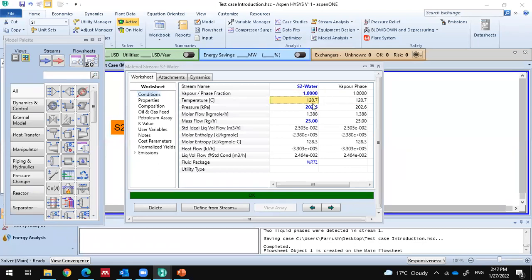However, since it is, as I told you, the saturation line, the temperature is constant. You need to add the latent heat of vaporization, or remove the latent heat of vaporization for condensation. So the temperature is going to be the same. Let us say for now we put it as 0, and we say that at this condition we have the saturated water. And let us change the pressure back to 1 atmosphere.